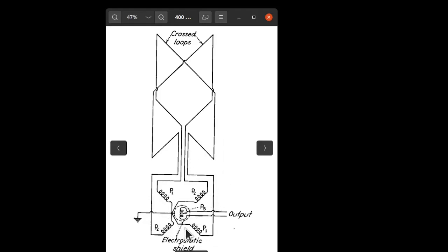This can be used to feed an Adcock design as easily, because if you notice, if we take out this element and this element, we have 4 verticals. The loops are not strictly necessary. They will impact the operation and the feed point characteristics, but we will still have the same radiation characteristics of the directionality rotating with the turn of this coil.